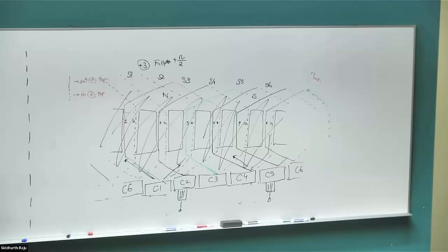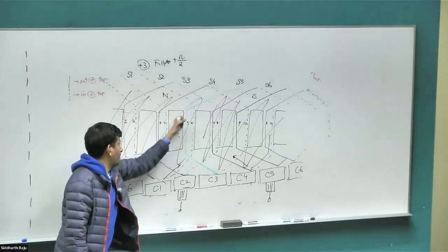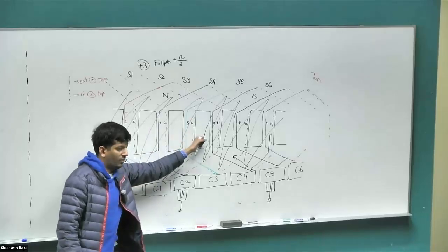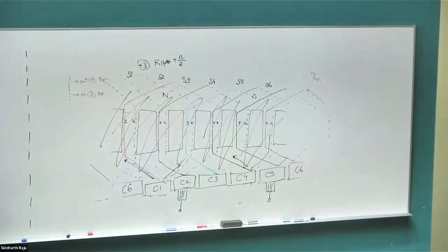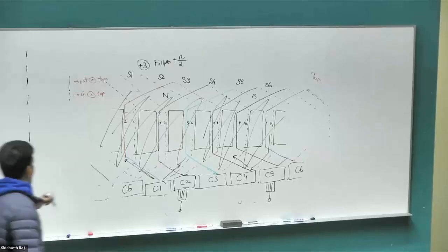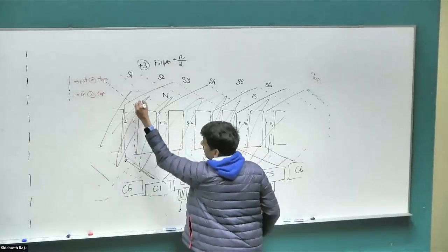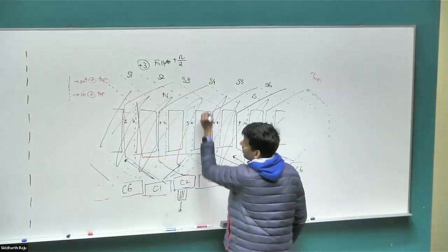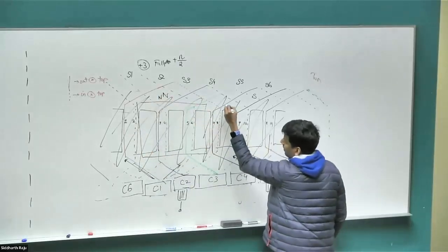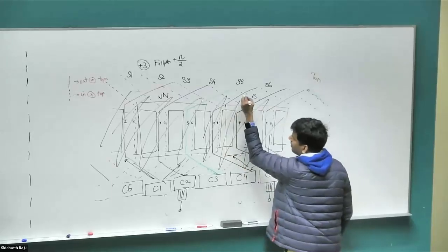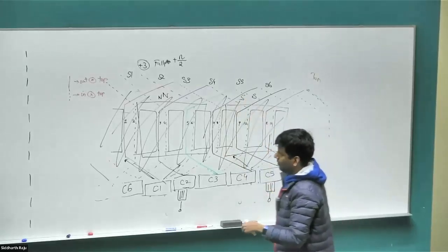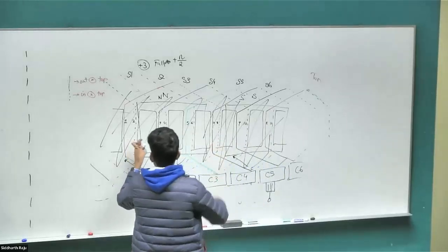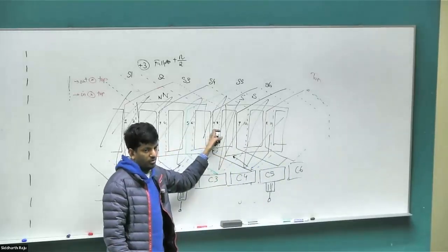The voltage. You need to ensure that the coil voltage across 2 and 7 and 1 and 8 is close to 0. That's the requirement. So when we created our magnets, we put them in such a way that they only cover a portion of these conductors and don't cover 1 and 2 and 7 and 8. That's why, at the correct angle, our magnets didn't stretch all the way. Our magnets only stretched to about 60 degrees, with this our north pole and this our south pole, or whatever angle that comes out to. So 1 and 2 and 7 and 8 are in the region where the magnetic field is very close to 0.